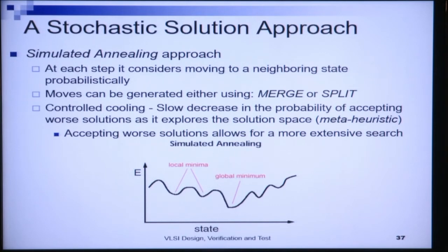That means my input is a conflict graph, and from that input conflict graph I have moved and obtained, at an intermediate state, a certain merging over the conflict graph. That means I have a certain number of operations clubbed together in certain resource instances of registers and functional units.